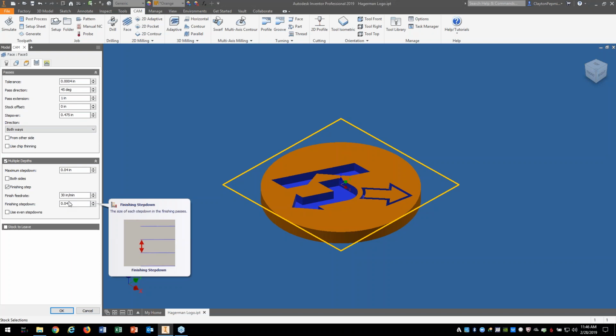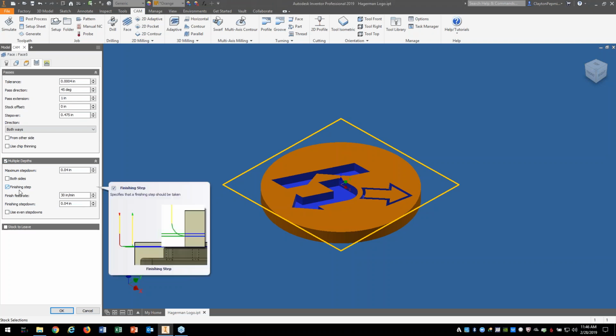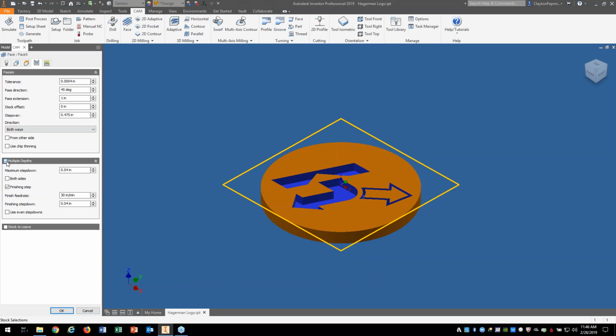Those are not recorded in that XML file. So even though I changed the value and said, remember these values, there's no way to tell it to remember to turn these on. However, I can go into that XML and add those lines of code to do that remembrance. You can't right click on this and say, remember that. They don't have that in here. But that doesn't mean I can't do it.